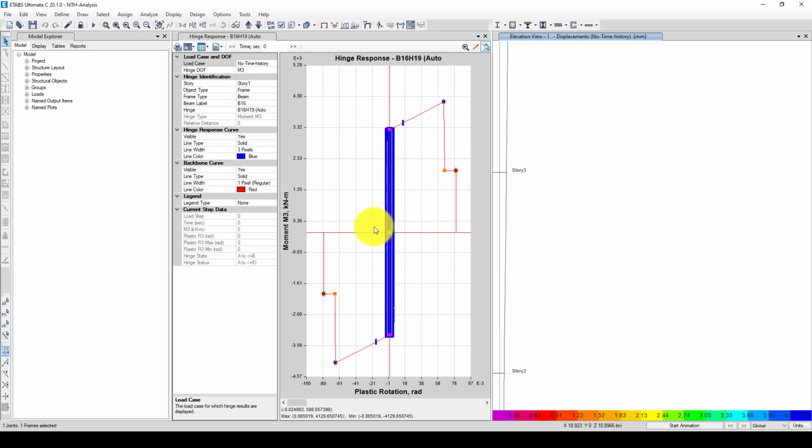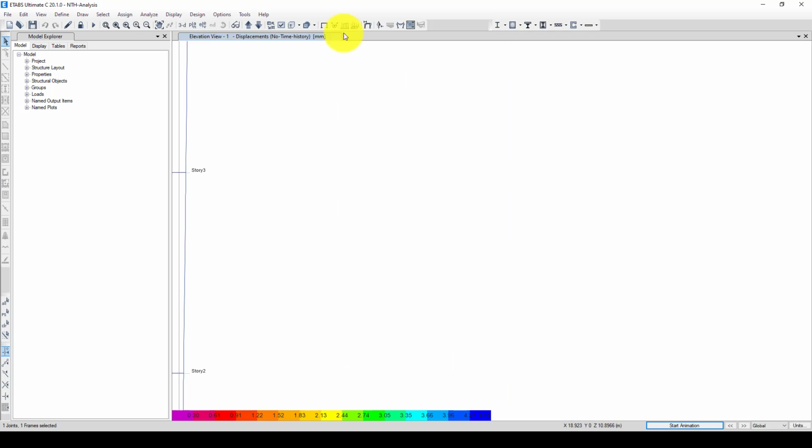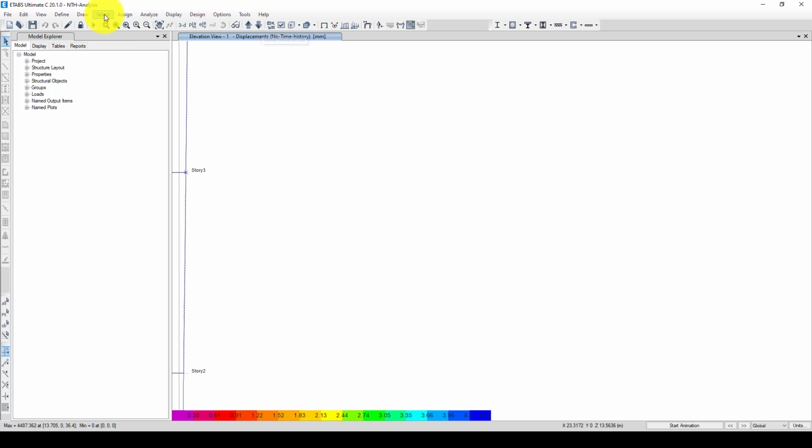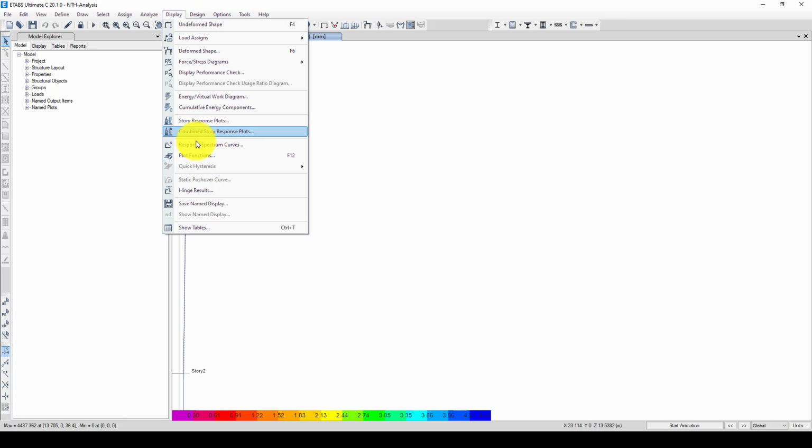Maybe we can define some extra material nonlinear behaviors, or also consider the fibers, that will give us a good result like this. I will show you how you can do this. If I go back to here, in the frame it's not activated. There is some sort of hysteretic behavior like Takeda, pivot, and other models, and you can use some specific one, and then you will see a little better hysteretic response of that one.